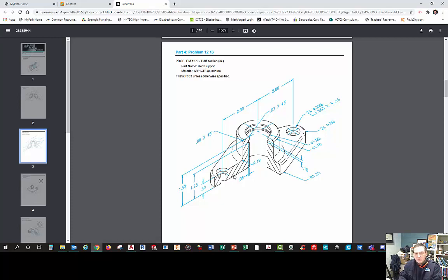No. They almost need a diameter to go off of so they can measure how far out, or if they're using a boring tool, it's not an exact straight cutter, it has an angle on it, or you can set it to where it goes in and goes into the side so that you can make that little indention right there. Well, I guess you could just put that distance right there. I'll have to talk to a machinist and say, hey, which is the better way to do this?